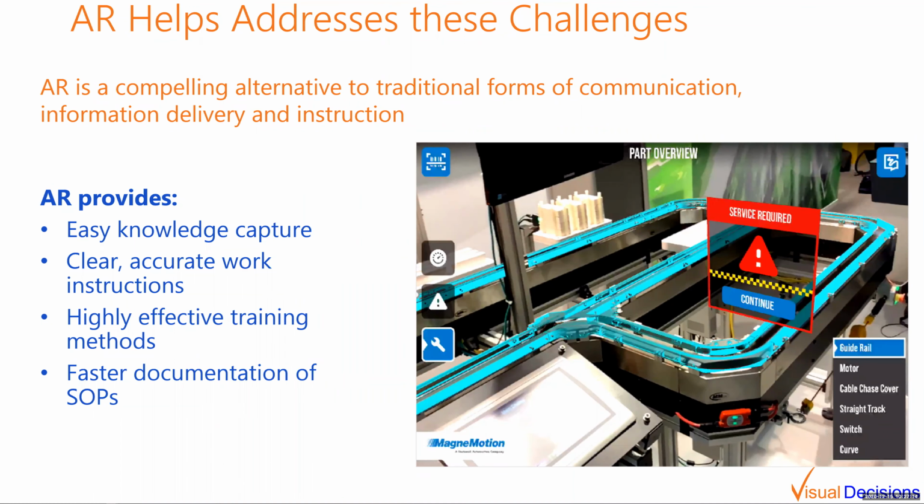With augmented reality, you have that opportunity now to help provide contextual information as someone is looking at the process itself. Not only in a situation like this, but I've seen examples of using AR for pick and place, where as a unit comes in front of an operator, the system will understand what SKU that item is, what parts are required at that station. It will highlight what is the first part that they're supposed to pick or which bin, and then where they're supposed to place that on the unit, and so on for the next part and so forth. And so it very much error proofs that process, where somebody almost has to try to do things incorrectly in order to grab the wrong part for that particular unit.